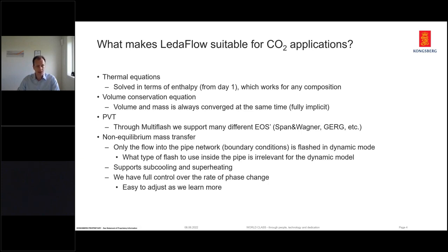This non-equilibrium mass transfer supports subcooling and superheating, which is physically correct. And we have full control over the rate of phase change. So this is a kinetic expression, and it's easy to adjust this as we learn more about how the system behaves.